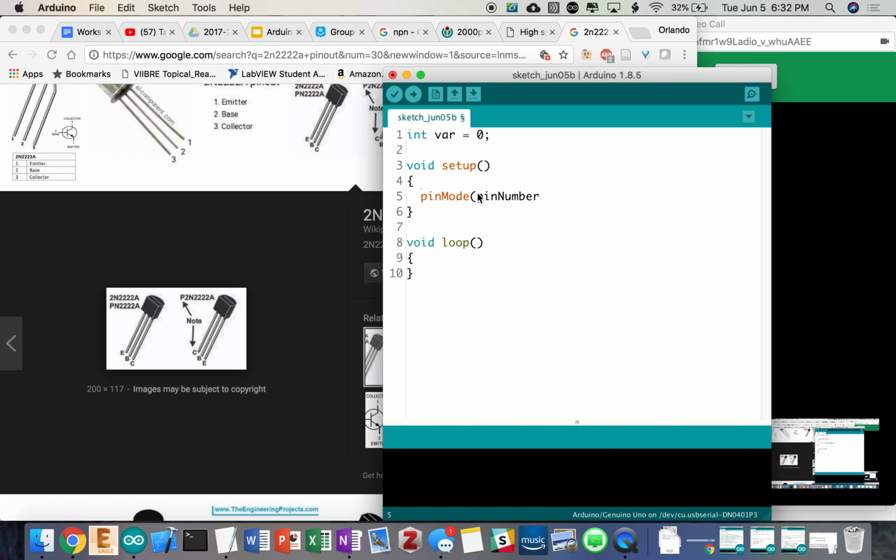If you look at the Arduino I gave you, you'll notice there are some things on each side. Starting from this side, it goes from 0 up to 13, right? Those are pins. These specifically are digital pins, so they either turn on fully or turn off fully. Down to your bottom left, you see analog in: A0, A1, A2, A3, A4, and A5. Those are called analog inputs. They take time-varying signals like sinusoids.